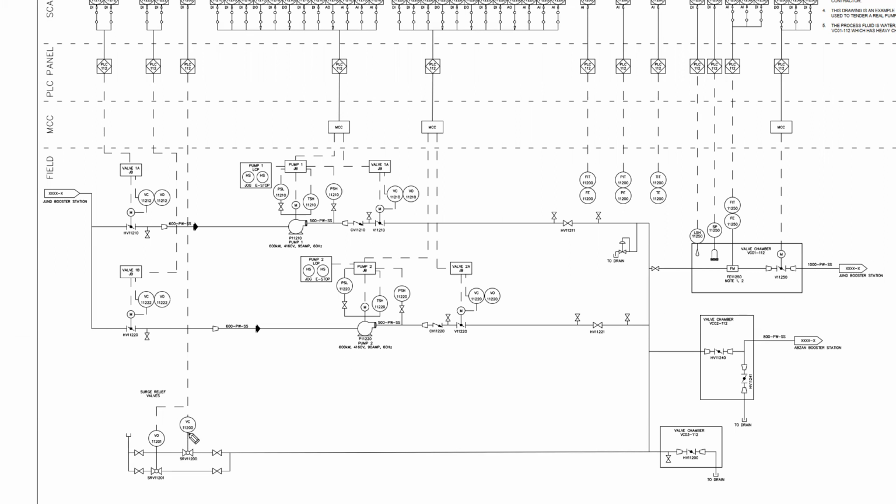I would expect to see a pilot line like this. Typically they'll monitor each other's line, something like that. So it'll be able to sense, okay, I'm opening, so I'll throttle one open and close slowly, because this is a normally open and normally closed. So they'll modulate back and forth to slowly allow a buildup of pressure through,